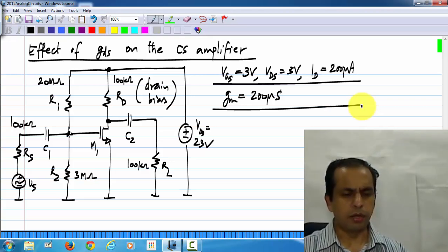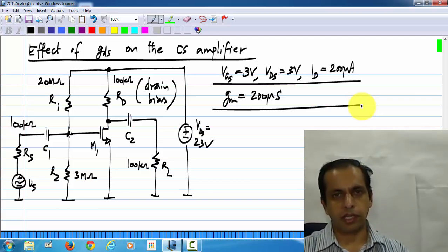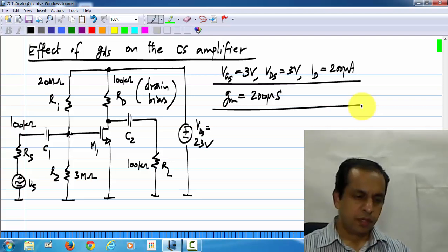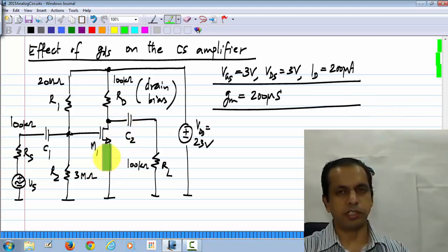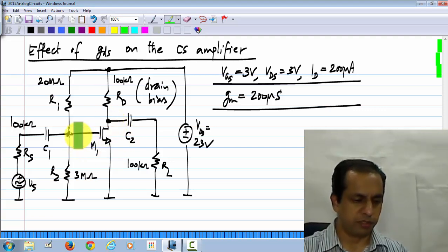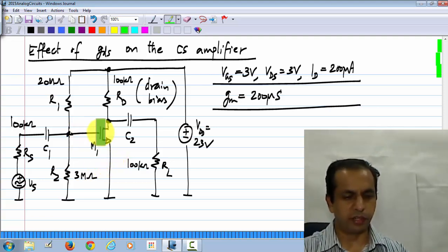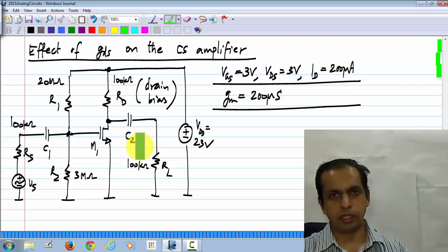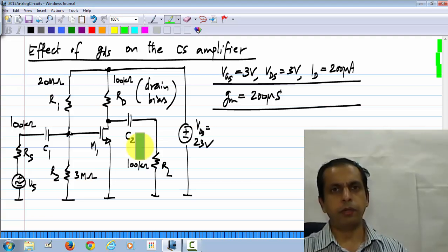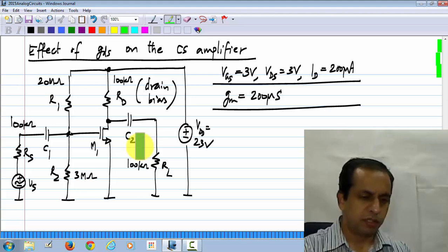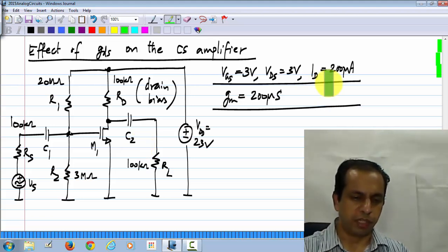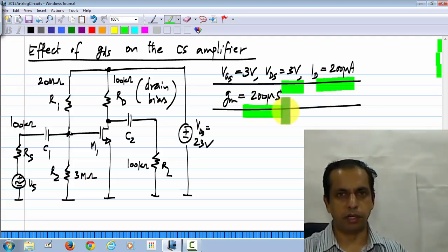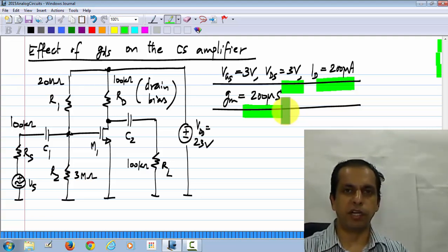Okay. So, now the question is, what is the effect of the channel length modulation, or the extra factor of 1 plus lambda VDS that appears in the drain current expression in the saturation region. As was discussed earlier, channel length modulation means that the operating point current also changes, because here we get VGS of 3 volts, that does not change at all, because the gate current is still 0, but for a gate voltage of 3 volts, instead of the current being 200 microamperes, it will be dependent on VDS as well, and you can calculate it. But like I mentioned, usually we do operating point calculations without taking into account the effect of lambda VDS. So, we will assume that ID will remain at 200 microamperes, and therefore, VDS will remain at 3 volts and so on, and similarly GM will remain at 200 micro Siemens. So, we ignore the changes in operating point because of this.